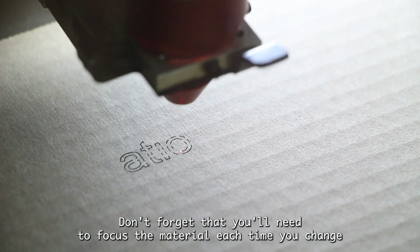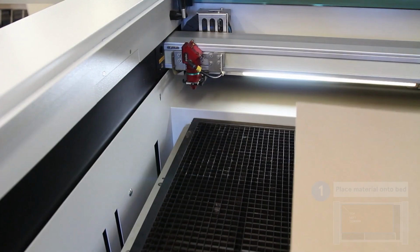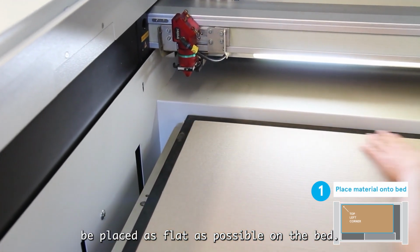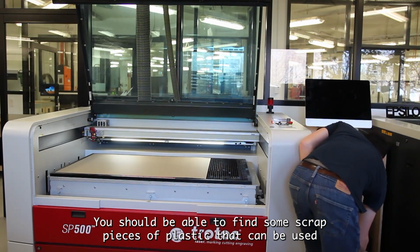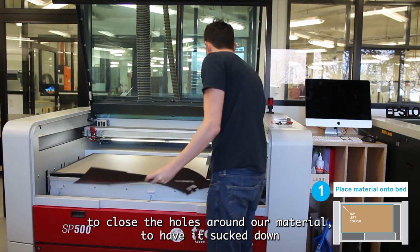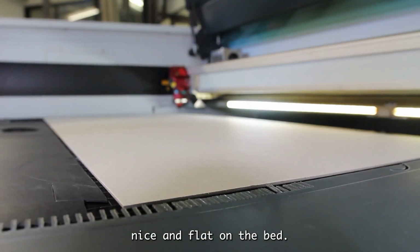Don't forget that you'll need to focus the material each time you change the thickness in material. The material needs to be placed as flat as possible on the bed. Make sure it's not riding up on this side lip. You should be able to find some scrap pieces of plastic that can be used to close the holes around our material to have it suck down nice and flat on the bed.